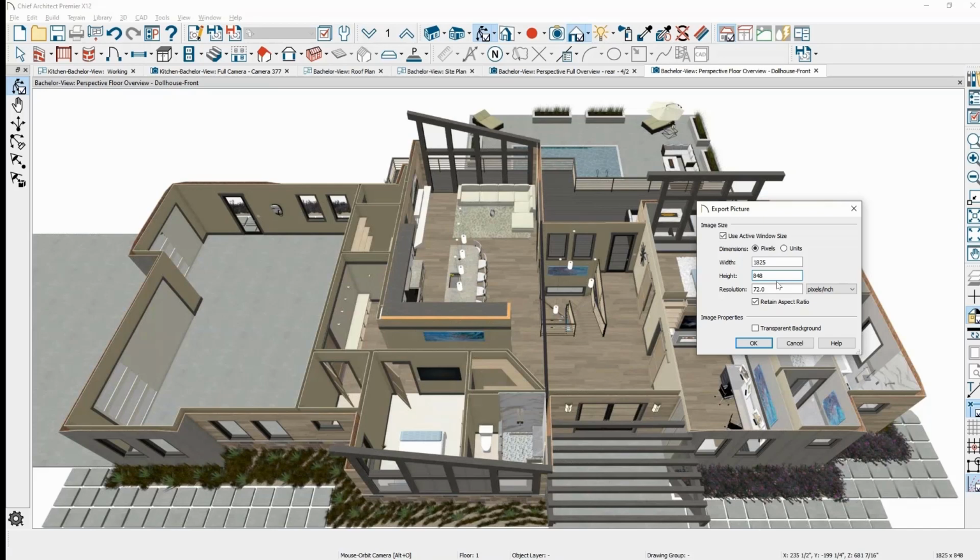I would recommend, if you're having trouble zooming in and it's getting blurry, to do the resolution at 300. Okay, so 300 and bigger. Yep, you can only get better by making it bigger, and the resolution, more dots per inch, means more detail. And really, Sharon, that won't take that much longer if you put that at 300 or 600 dots per inch, unless you're ray tracing it. At that point, you start to pay the price for that.